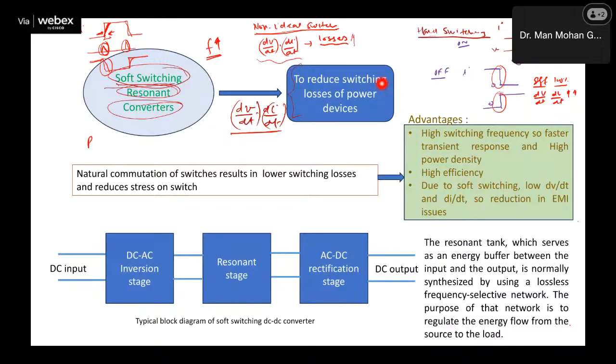And we know that this P average in case of non-ideality was V I on upon Ts, which is into frequency, into t on plus t off. If you remember, we discussed this formula, we derived these formulas. Okay, so now this formula suggests that